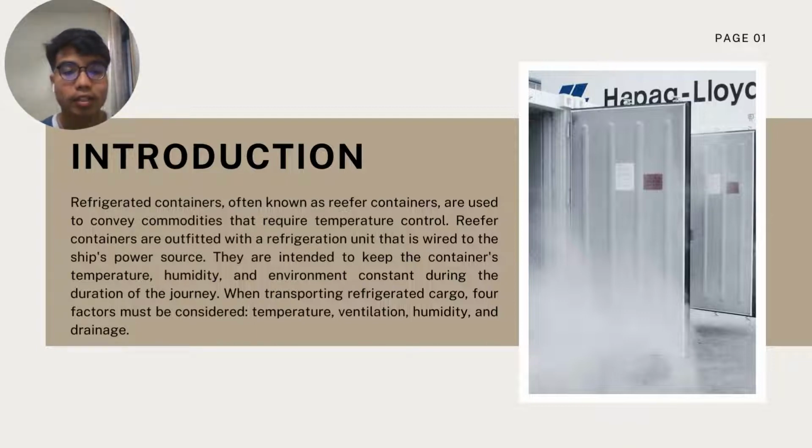For the next factor, which is ventilation, air must circulate through the cargo at all times to remove heat and gases in order to maintain a cool temperature. Therefore, shipping containers must have ventilation. The next point is humidity. Some items benefit from a decrease in humidity levels. A reefer unit's dehumidification function can reduce the air's relative humidity. Although some modern units can reach 50% relative humidity, the norm is between 60 and 85%.